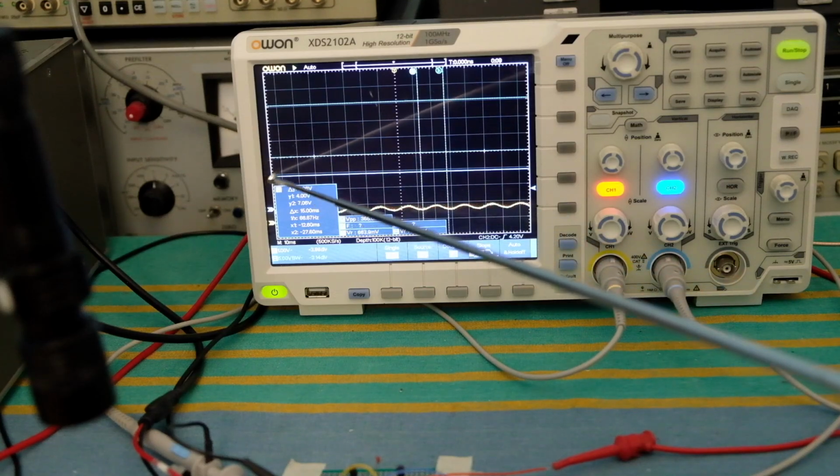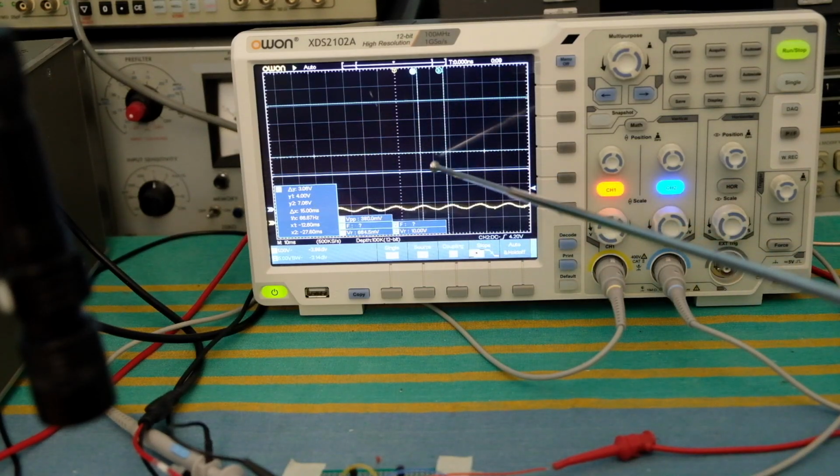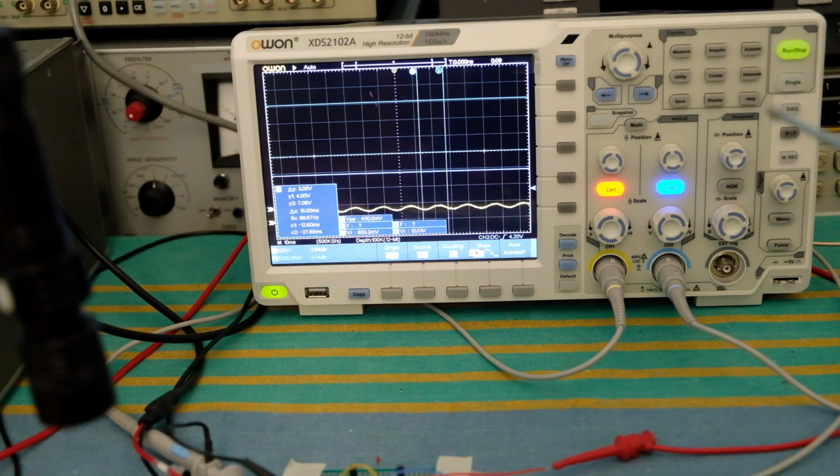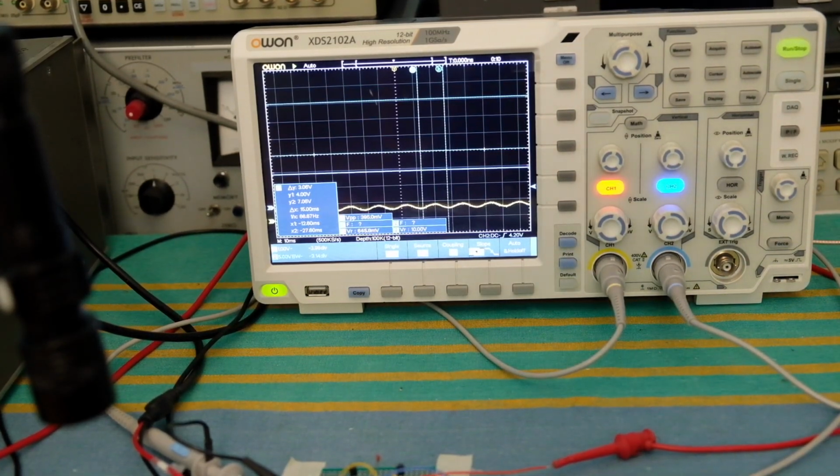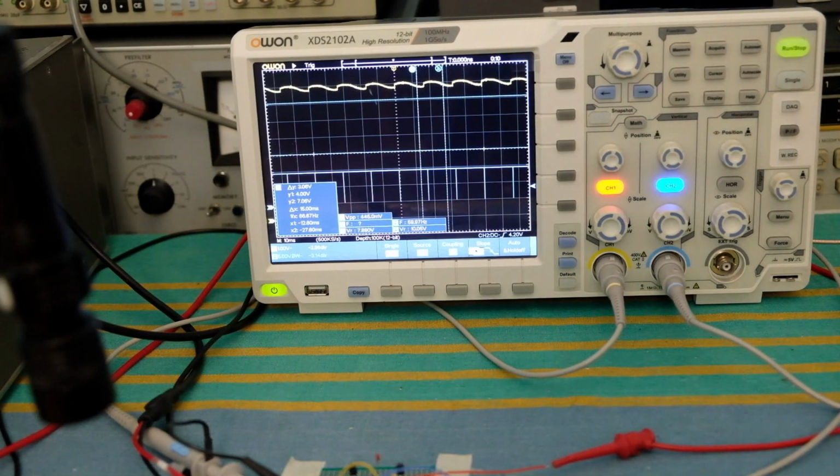And the blue curve over here is the reset pulses, and they're going to be very, very narrow, on the order of 10 microseconds, and the total integration time is about 16 or so milliseconds, so you'll see that it's barely a very short spike in that waveform. So I'm going to turn on the reset now. So there you have the reset turned on.